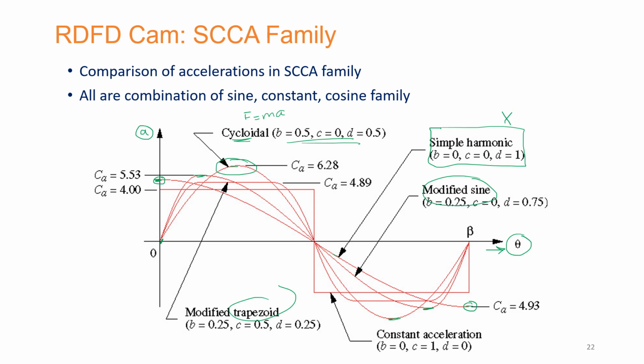In case a design engineer finds it difficult to decide among different versions of the cam profiles, this kind of curve is going to be helpful in a sense that it is going to give the designer some deeper sense of understanding of which profile is going to create more forces when you try to move, in case of acceleration. Another diagram can be used for the velocity to find out the velocity profile. We're going to see that in the next.